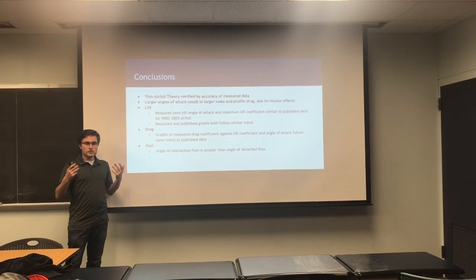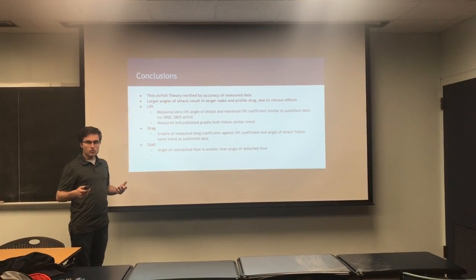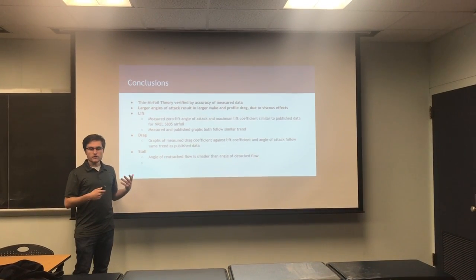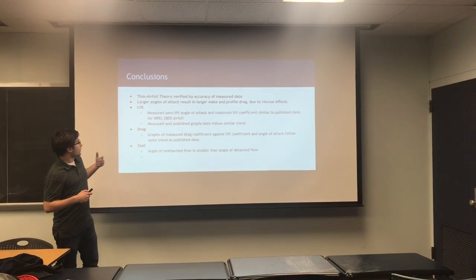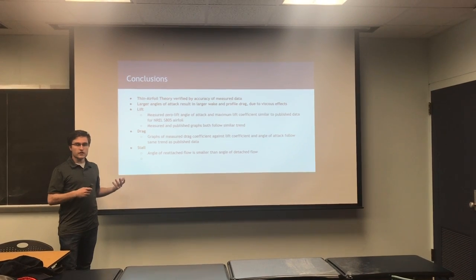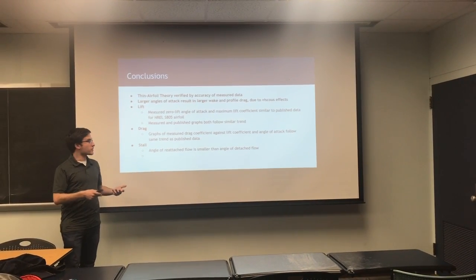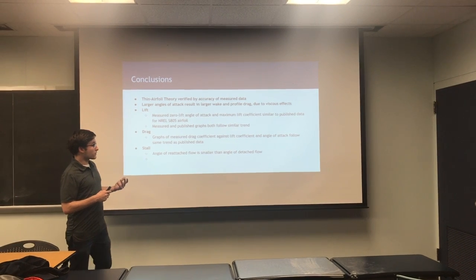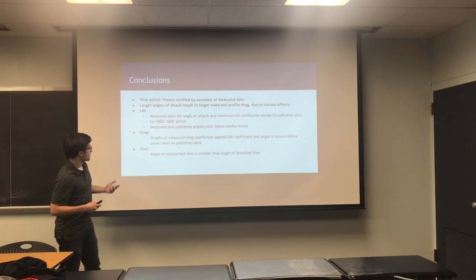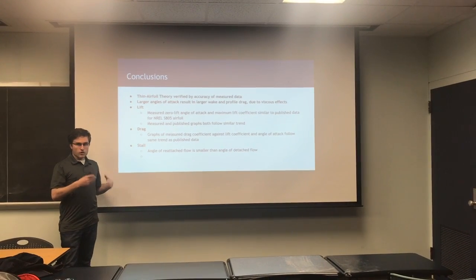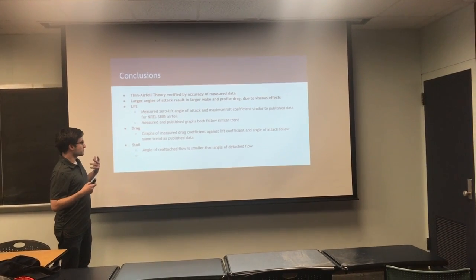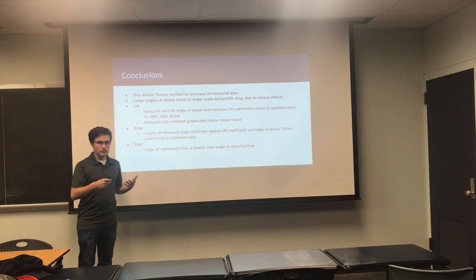We also demonstrated the effects of viscous flow over an airfoil. And all the effects that we measured in our lab would not have been present at all if the flow were perfectly inviscid. When it comes to lift, the measured zero lift angle of attack was the same as the published data. The maximum coefficient of lift was about the same, and the trend was the same. When it came to drag, the rough drag trends were the same as published data, as were the maximum and minimum, about the same.